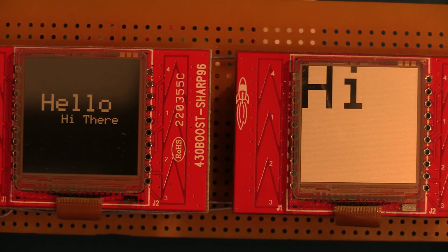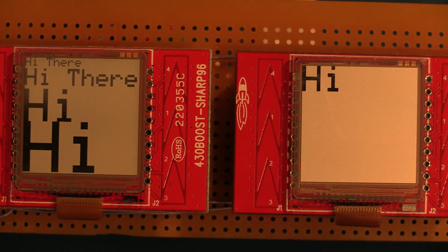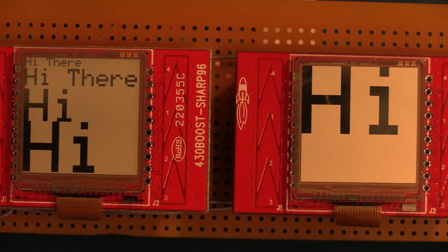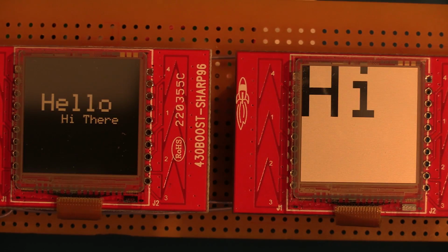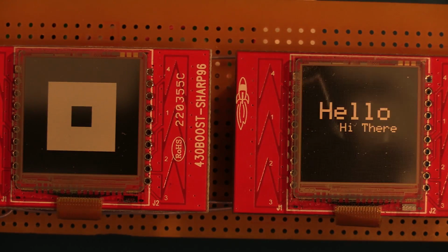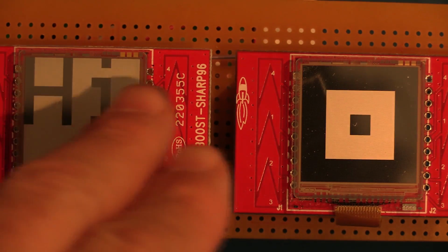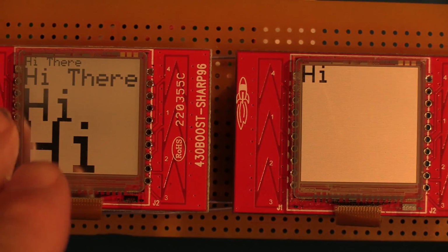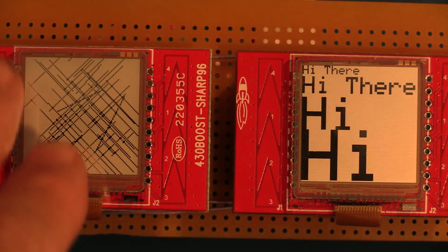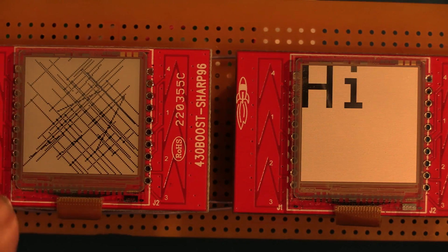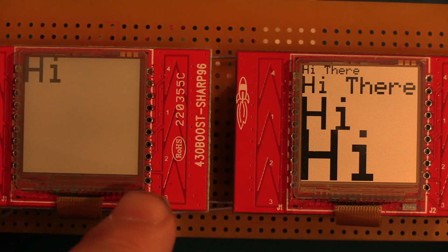And obviously this is all written in C#, and I had to make it work for these displays in the way that these are put together, because they have some nuances, and when we go through the code you'll see what that is. I think one of the biggies is the fact that the display addressing is actually backwards. When you output the data, the least significant bit is on the right of each byte, and the most significant bit is on the left, which is how you would normally think about it. But when you actually address the rows, 00 is top left and 96 is on the bottom, and then 0 is on the left from a pixel base to 96 on the right.